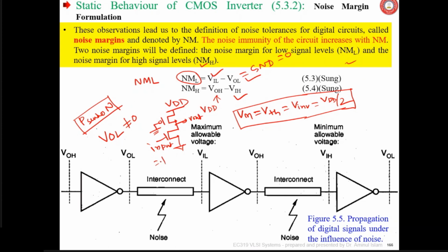If you apply 1 here, the NMOS is on and is going to pull the Vout node, the output node, down towards 0. While doing so, it has to fight against the on PMOS. So its output is not going to be a proper 0.